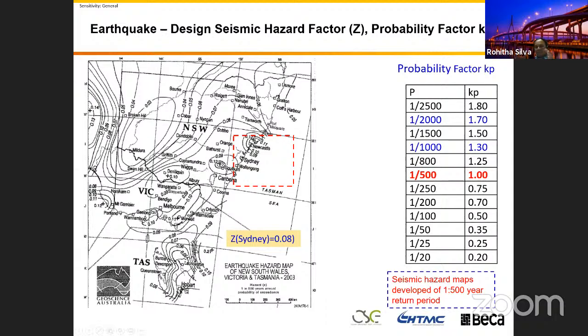You see, the higher the importance level of the bridge in the same place, that's what I want to explain to you. In the same project, in two different places, on the same bridge, you can use two different earthquake approaches to design the bridge, because the level of performance requirements is different.